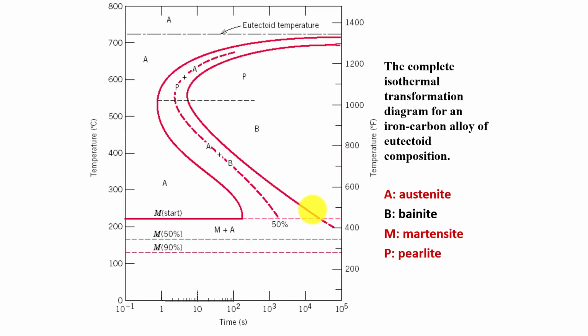Now, another thing that we've talked about is this wonderful isothermal or TTT diagram, time temperature transformation. And we talked about the fact that when we quench something, we want to get in front of this curve right here, the nose or the knee of this curve. And the more carbon we have, it moves it to the right. And we want to get martensite start and finish so we can get primarily a martensitic looking needle structure that's feathers. And that's going to be this good, strong stuff. That's why we would like to heat it up and quench it.